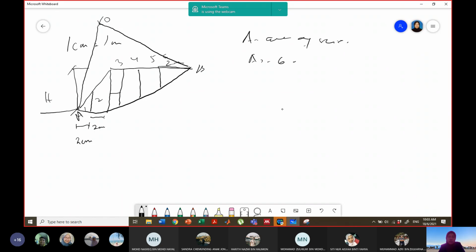We are going to use the trapezoidal area. The trapezoidal formula for area is a half times B times (H1 plus H2). As I said again in the last class, H1 and H2 are measured on the left and right sides of the vertical slice. Okay, let us take slice number 1 here.